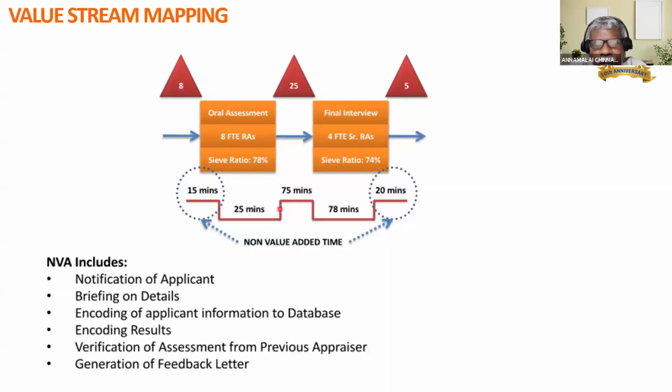You make an action plan, implement the action, and then after implementing the action, wait for 2 to 3 months for the improved process to stabilize, and then you do the value stream mapping again. Since you have taken action on the choke point, you will find that the flow has improved and your problem has been greatly solved.